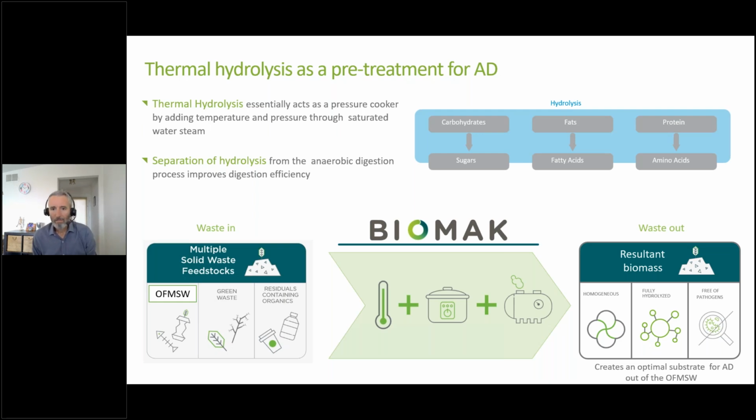On a typical anaerobic digestion process with a 28-day residence time, hydrolysis might take 10 to 14 days of HRT, meaning that maybe half of your total residence time is dedicated to the hydrolysis stage. Now, if we take that stage out of it, if we do it before, then the residence time will fall to probably half. So your residence time that was 28 may now be 14 days. Next slide, please.